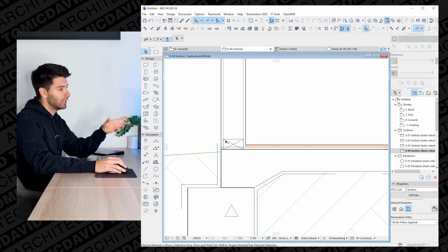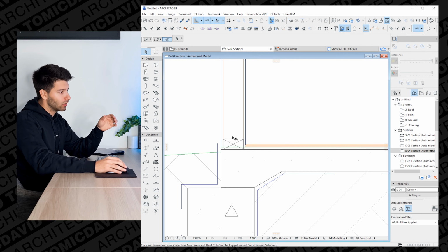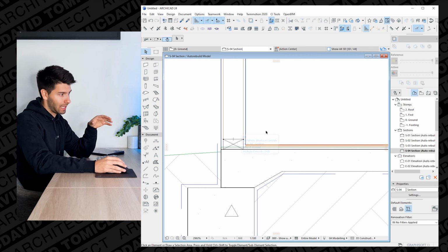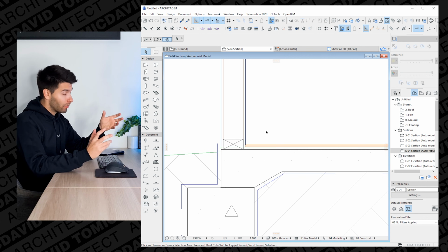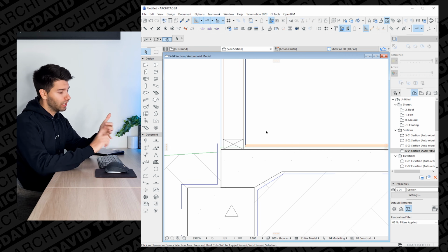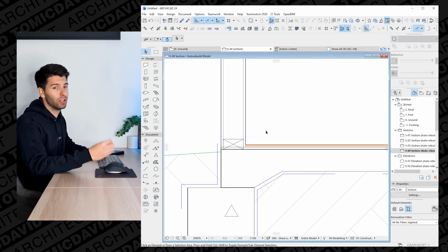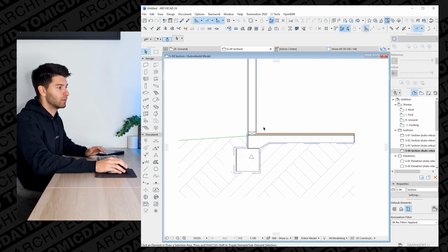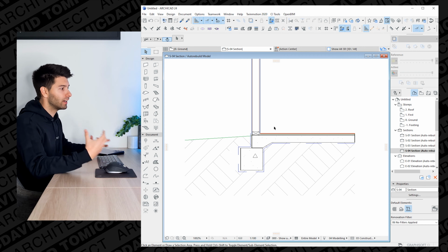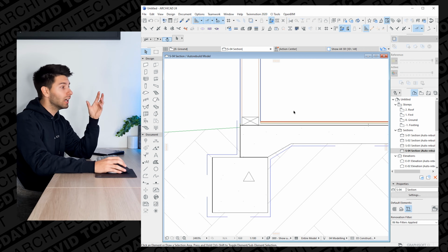Now, finally, to make this detail completed, there would be a bolt or a screw or some sort of concrete anchor sitting on top of this bottom plate, going directly into the concrete slab. Now, depending on a number of factors and what the engineer determines, it could be just your typical concrete screw, it could be chemi anchored, it could be a whole bunch of variety of things. So that will be determined by the engineer. It will be very site specific, so I'm not going to draw it in, I'm just going to articulate it so you're made aware.